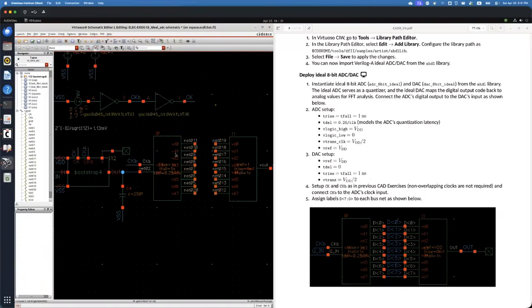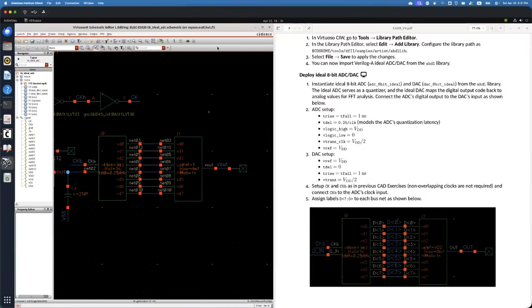And a small tip is that if you press space, you can automatically assign some net name. For example, here, press space. Then you can do it this way. And if I save it, it is assigned this way. And if you erase all of this, then for example, let me do this, this way then.